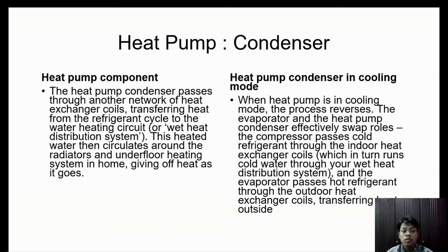Lastly, the heat pump condenser in cooling mode. What does the condenser do in cooling mode? When the heat pump is in cooling mode, the process reverses. The evaporator and the heat pump condenser effectively swap roles. The compressor passes cold refrigerant through the indoor heat exchanger coils, which in turn runs cold water through your wet heat distribution system. And the evaporator passes hot refrigerant through the outdoor heat exchanger coils, transferring heat outside.